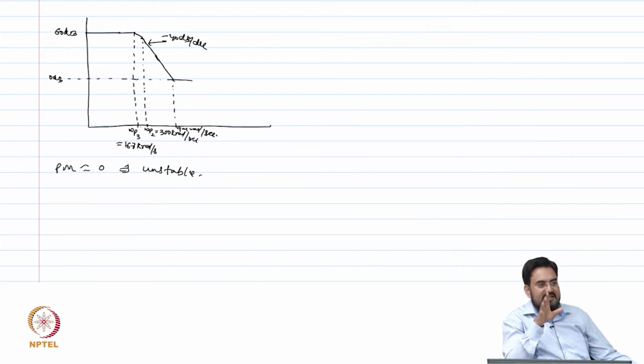So remember, for 60 degree, let's say I want a 60-degree phase margin, your second pole, or the non-dominant pole, should be roughly 1.7 times of your UGB. So omega P3 is now fixed, we cannot change that, which means your UGB should be 1.7 times less than omega P3.